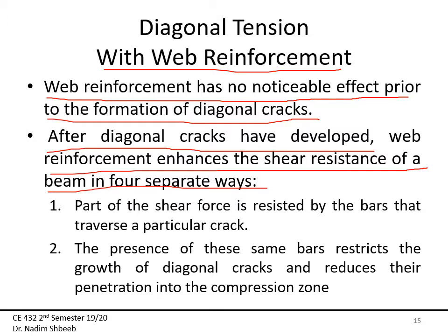So again, it does not have any influence before the shear crack develops, which means it does not prevent it from developing. Okay, so as long as there are no shear cracks, there is no stress in the shear reinforcement. But the minute that crack begins to start, then we will start seeing some stresses in the shear reinforcement. So they do not prevent the formation of shear cracks. They are just there to help when they do.